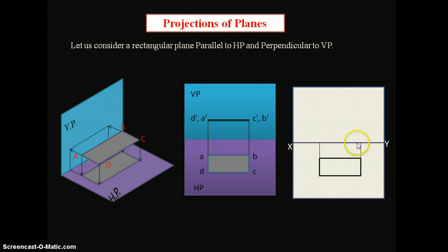So again draw two lines aligning to the projection lines we have drawn for the top view. The length of the projection lines should be equal to 30 mm, because it is 30 mm over the horizontal plane. Then join the two endpoints of these projection lines. Automatically we get the front view, that is a straight line.